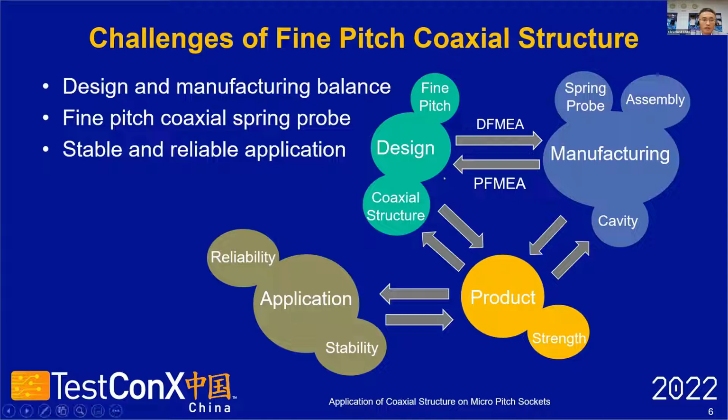The major challenge of applying coaxial structure on a fine pitch socket is to balance the design and the manufacturing capability, and ensure the complete product has consistent manufacturing quality, especially for the signal spring probe strengths.